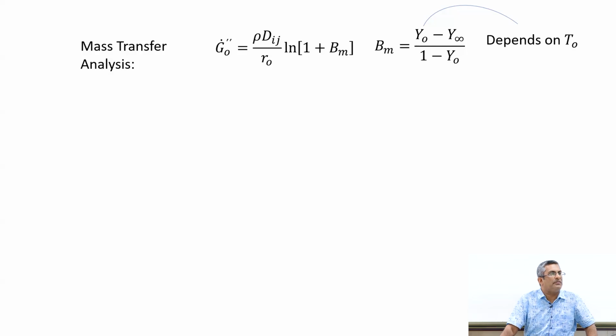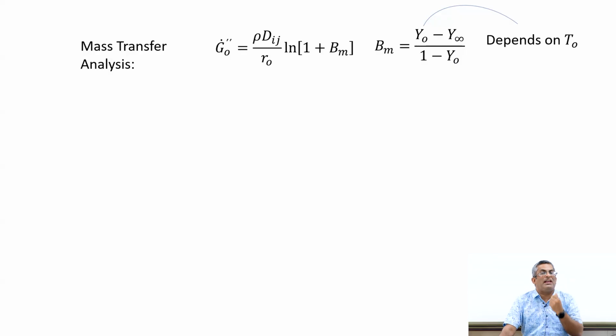Now, if evaporation is taking place, what would be the temperature of the droplet? Can it be 25 degree? If you argue that yes, it is 25 degree, then if both the ambience and the droplet are at 25 degree, can evaporation take place? How will heat transfer happen? See, for evaporation to occur, heat has to be transferred from ambience to the droplet, right?